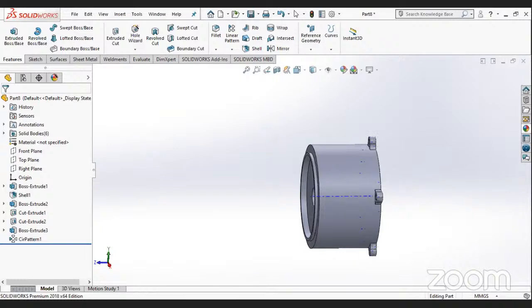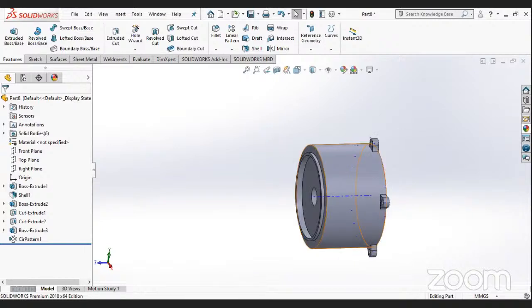Then we'll go to make this box which is here, on which your cylinder is going to rest, which you will do in assembly. So the dimension is given in the earlier picture of our cylinder, so that was 85 by 85.